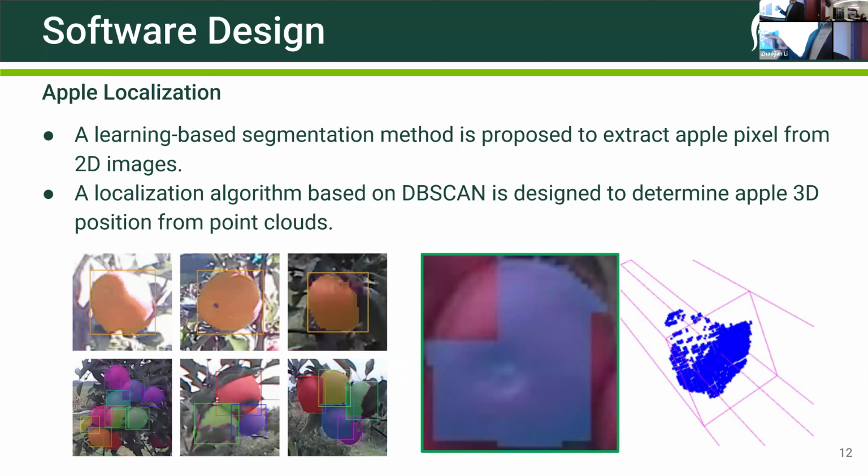So the next part: here I'm showing a sequential approach. We do detection, then we do localization. You have bounding boxes of the fruits, and then we do localization. Localization is actually quite challenging for this application. First of all, this is outdoors, so some of the cameras that work really well indoors, for example the RealSense, just don't work outdoors. It's also a very complicated background, with multi-layer occlusions and challenging lighting conditions, and we also require high precision. We want millimeter level accuracy. That's why this is a very challenging part, and we spent a lot of time on it.